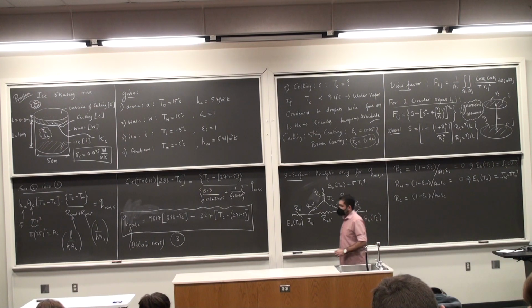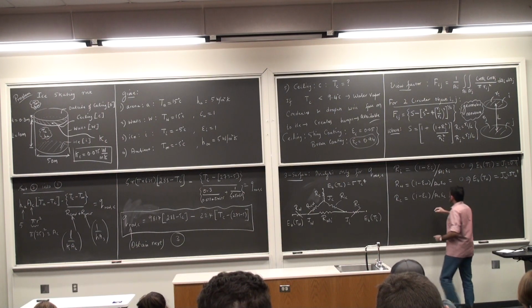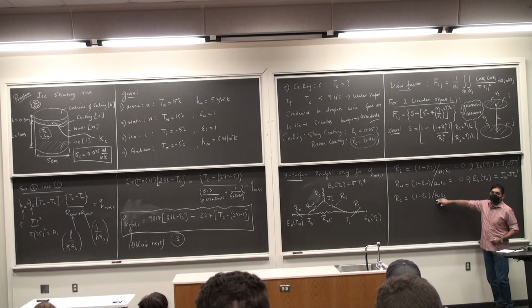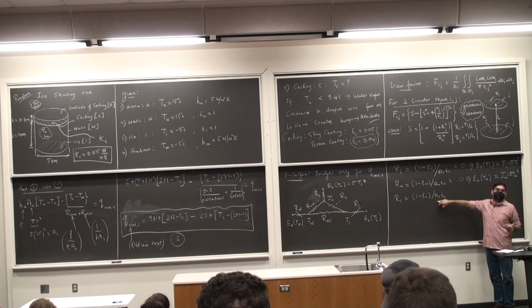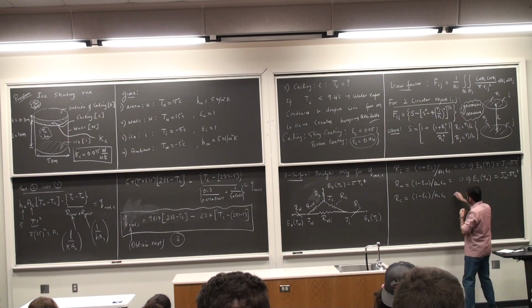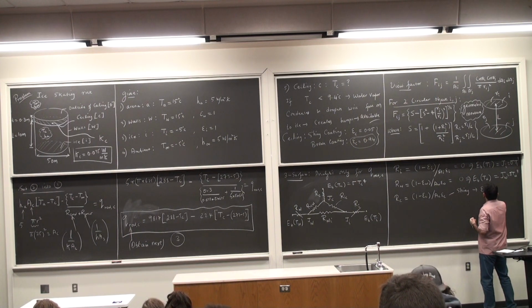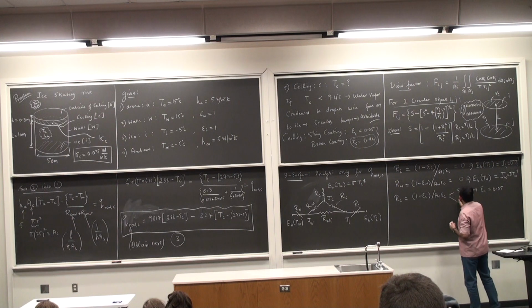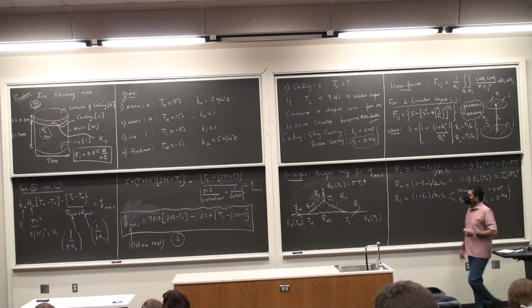All right. Then the remaining ones, which are the geometric resistances, I have the following. Now here I have a problem, right? Because I have to calculate it two times. One is for the shiny ceiling and the other is for the brown coating. Okay, so this could be calculated for the shiny, where epsilon c is 0.05, and then the brown coating, epsilon c is 0.94. So I have two paths that I need to follow here. I'll list the geometric resistances as well.